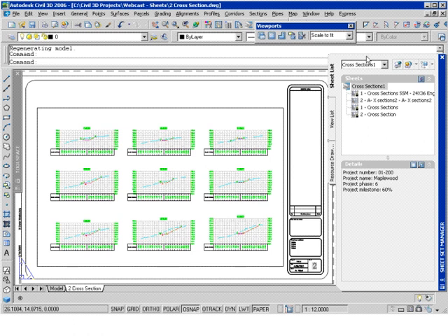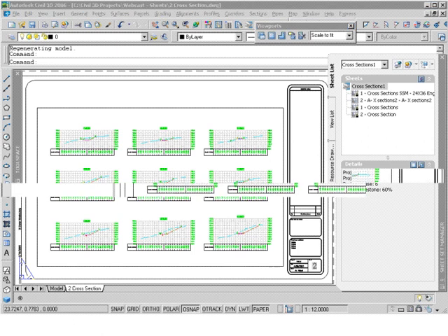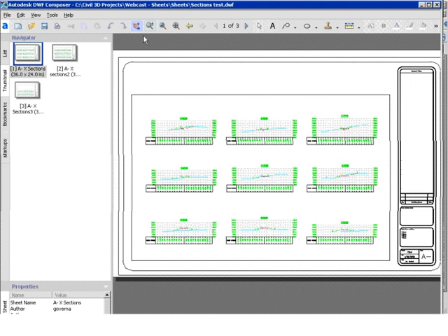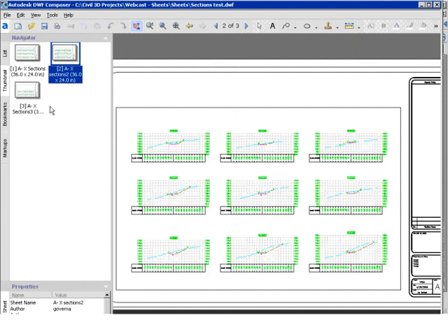And again, that's where we're pulling those page setups. So this is all just automated. With just one click here, I select publish, and now it's going to take all of my sheets and send them either to a plotter or to our DWF. So what I'm going to open up here is DWF Composer, and we'll see that here are those same sheets actually in a DWF. So I can ship this off to the contractor, I can ship it off to my project engineer who needs to take a look at these and redline them, so on and so forth.